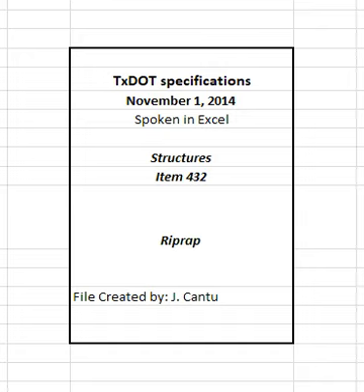5. Payment. The work performed and materials furnished in accordance with this item and measured as provided under measurement will be paid for at the unit price bid for riprap of the type, thickness, and void filling technique (dry, grout, mortar) specified, as applicable. This price is full compensation for furnishing, hauling, and placing riprap and for filter fabric, expansion joint material, concrete, and reinforcing steel, grout and mortar, scales, test weights, equipment, labor, tools, and incidentals.